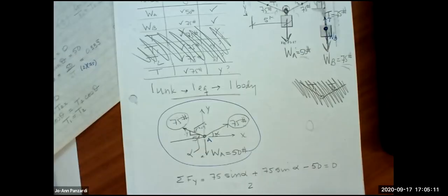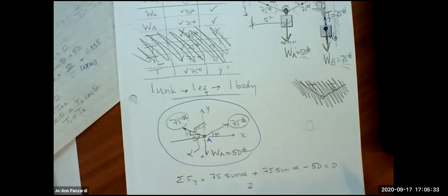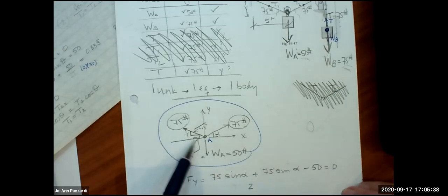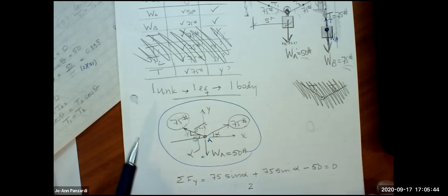If you used cosine, would you need to do some 90 minus alphas? We probably wouldn't want to do it. You don't want to solve a statics problem with cosine or sine of 90 minus alpha, unless you remember all those trig functions, which I don't. They are just a Google search away, but I would just stick to not having to do that. I would not do ratios if there's a distance that's unknown, and I would not do cosine or sine of 90 minus alpha.